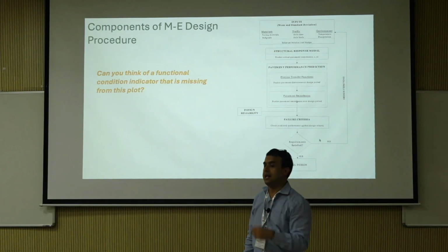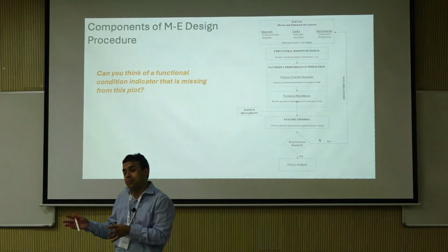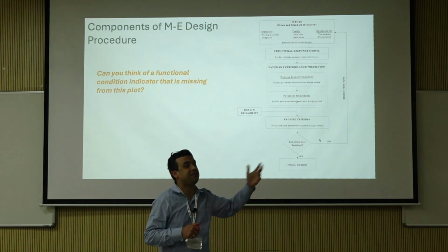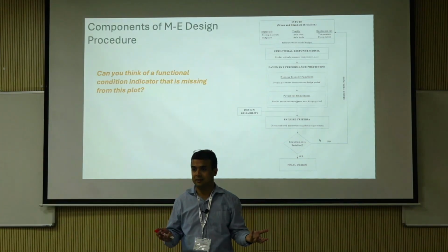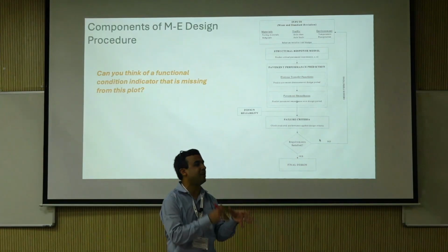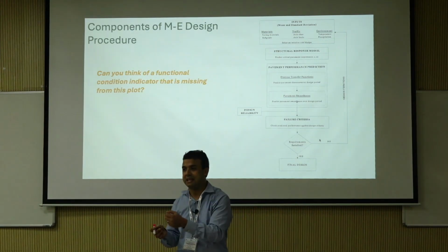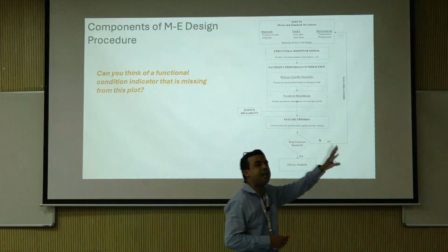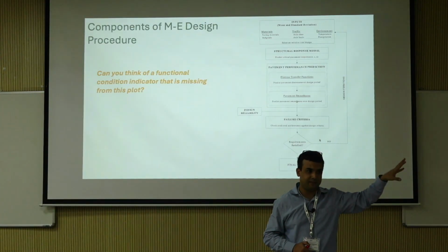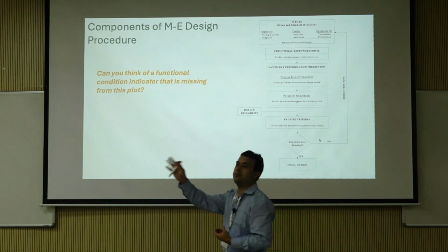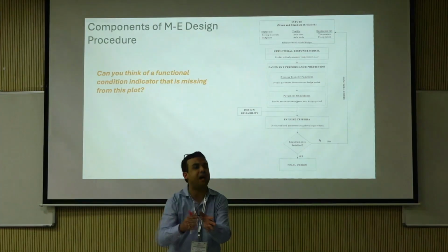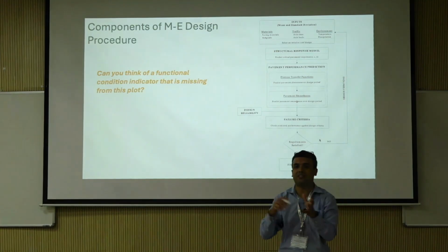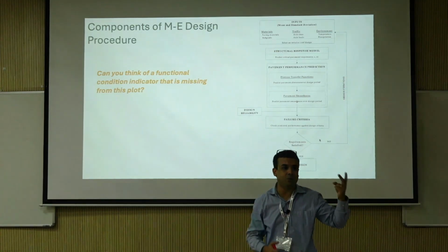Okay. Level 2 is you have some information, but you don't have everything. Let's just say the resilient modulus test device breaks down, you can't run it. But you probably are able to run CBR, you're probably able to run DCP. And then you use what are known as correlation equations to predict resilient modulus from CBR, from DCP, from R value, from density, something. That's called level 2.